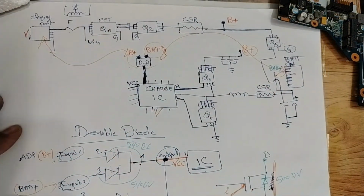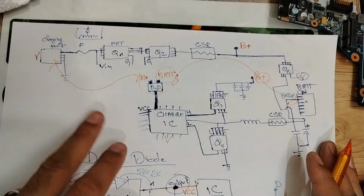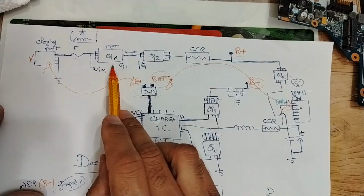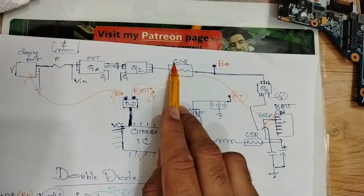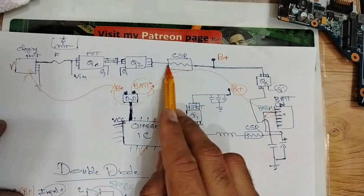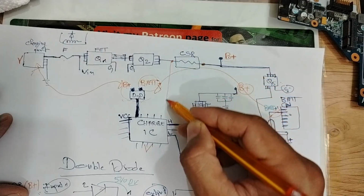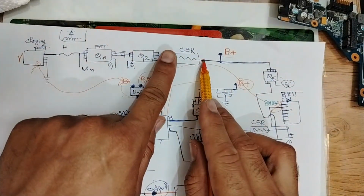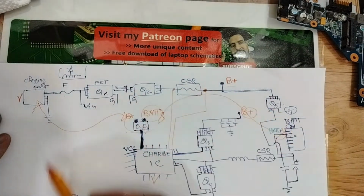Okay, but before reading some comments, let me see here if we missed something. We have the power jack, we have the fuse for protection, we have basically the two MOSFETs. I told you in some motherboards you can find just one switch. We have the CSR, or current sense resistor. This current sense resistor is connected to the IC, my friends. It senses and measures the amount of current consumed by the whole motherboard.